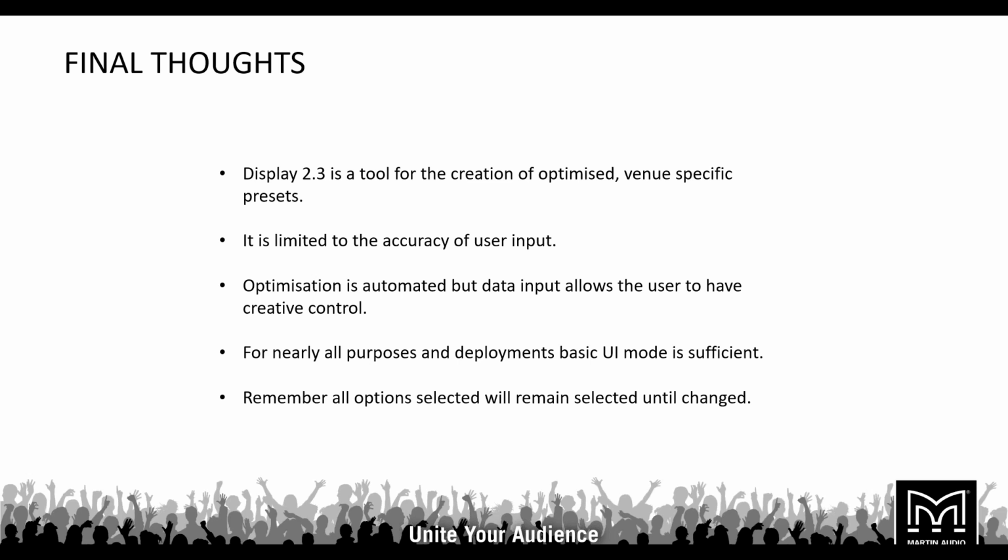I can think of an application that I was supporting a few years ago where it was a big student party with a DJ stage, big line array, and they really only wanted to cover the first 100 feet on a 400-foot long venue. But the thing is that from 100 to 150 feet, it was an F&B area. So we really went to the extreme with that SPL profile before we applied non-audience and hard avoid because there was no need for that. So it gives you a lot of creative control in those type of situations.